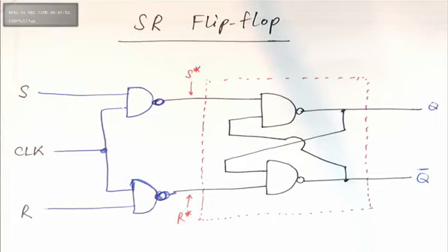All right? Shift RCL. So what are you doing? At that point in time, whatever is available, that's what you are storing. Now, that's what clock does. Clock gives us control over the circuit. The latch, even though it is capable of having memory, has no control as to when to take the memory. You want to press a button saying now, stop, like a stopwatch. You want to press stop or lap now. So the clock line is a control line.